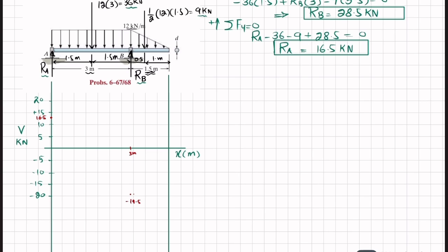Now you can see that this load is a horizontal load with 0 degree, so shear force will be 1 degree higher, and this load is downward, so the slope will be decreasing. It will be a first degree line and the slope will be decreasing.